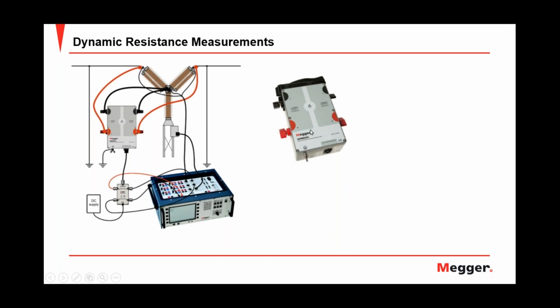So practically we are using a smart way to inject current during the operation with a super capacitor based supply, where the injection of current is triggered by the TM1800 just for a very short time during the operation of the circuit breaker only. As a result, we can inject quite a high value of current from a very light box and quite small as a size. So from one box, SDRM 202, you can test a 2 break per phase circuit breaker. Of course, if you have multiple breaks as 2, 4, 6, you need one box for at least 2 breaks per phase.